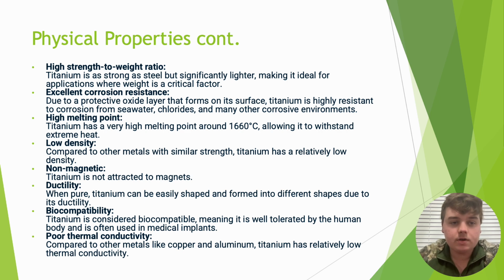Titanium is as strong as steel but significantly lighter, making it ideal for applications where weight is a crucial factor. It has excellent corrosion resistance due to the protective oxide layer that forms on its surface. Titanium is highly resistant to corrosion from seawater, chlorides, and many other corrosive environments.